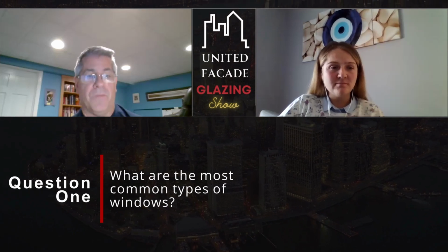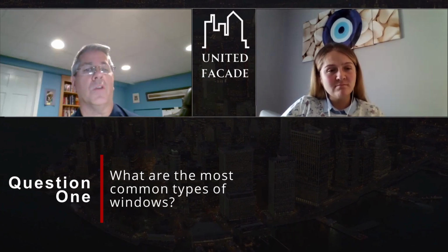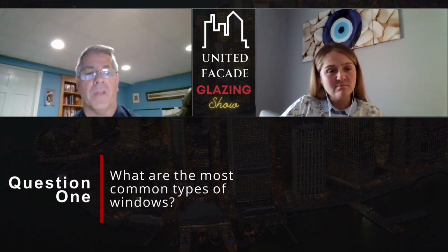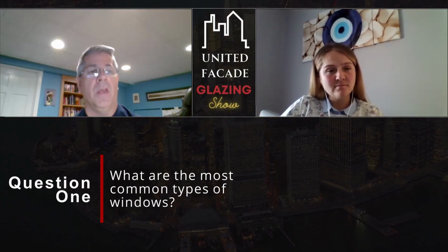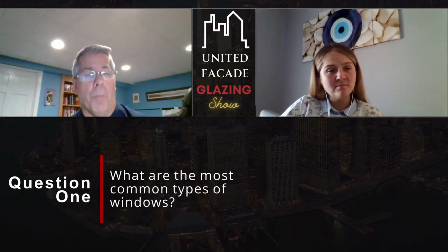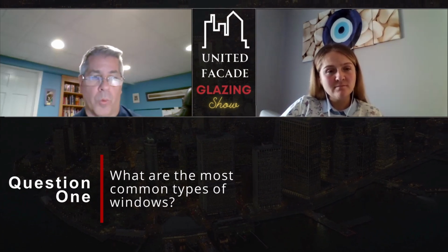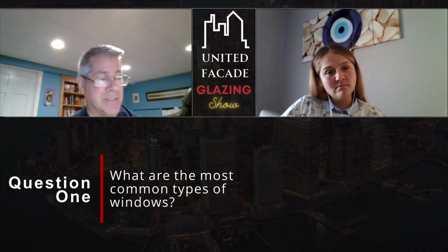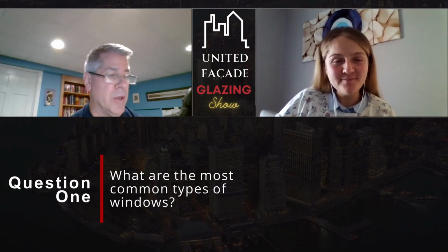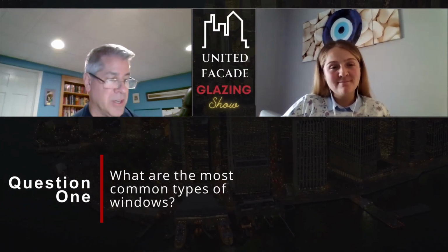And there are specific limit locks that you have to put on the window that meet a specific code that it has to withstand 400 pounds or whatever each specific locality requires, a specific poundage, so that it can't open more than that size with that amount of pressure applied to the window. Yeah. So it's a requirement, and I know that's in several cities as well. Also, I'm sure that's something that's in Europe as well as the United States.